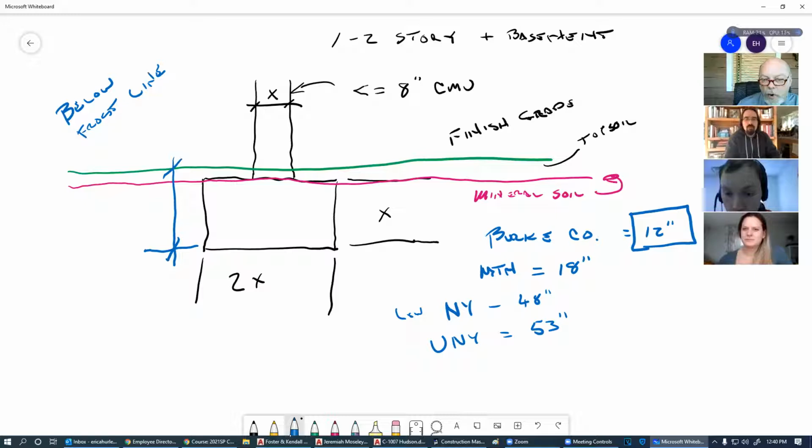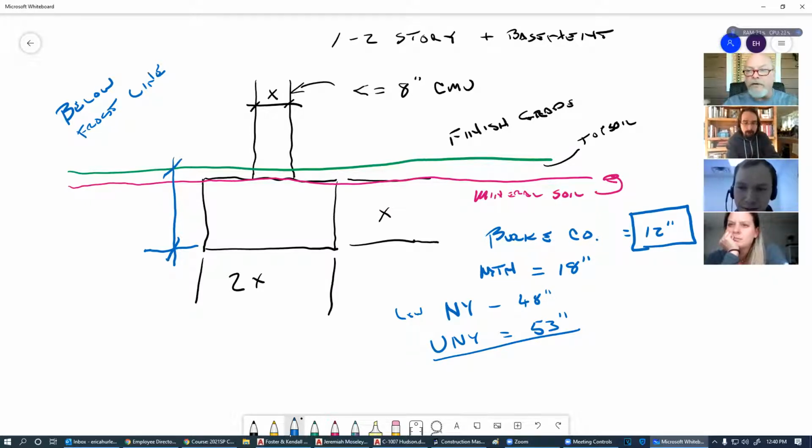And the further you go up north, the deeper and deeper and deeper it gets until you get up to a point well above the Arctic Circle where the ground does not thaw. And then it goes back to zero. You can just put your foundation directly on the frozen ground, permafrost, and it's going to stay for a while until the planet warms up a little bit more and all of that ice starts to melt a little bit more, and that turns into dirt and mud and crap, and the house starts sinking.